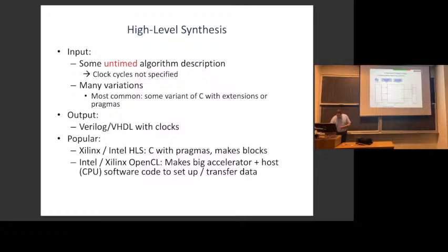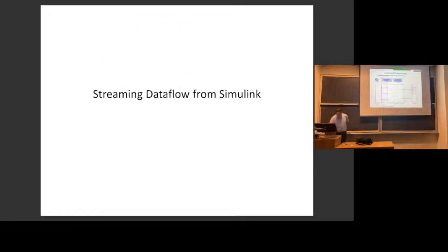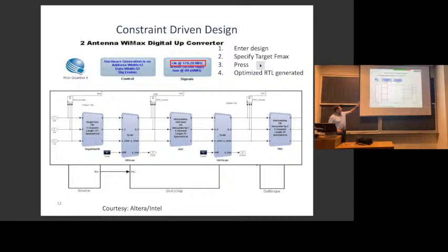Okay, so you give a little bit of extra information to the hardware generator, saying, what's my target clock frequency? What data width do I want? So I want to use 32-bit data. I think that's enough for my accuracy, and so on. You enter the design by just making that flow chart and entering little bits of extra information, like clock frequencies and data widths. And this particular example here is a finite impulse response filter.